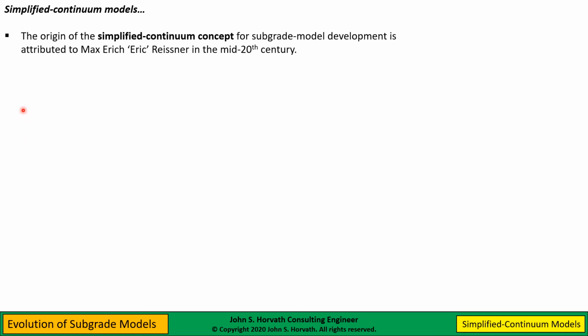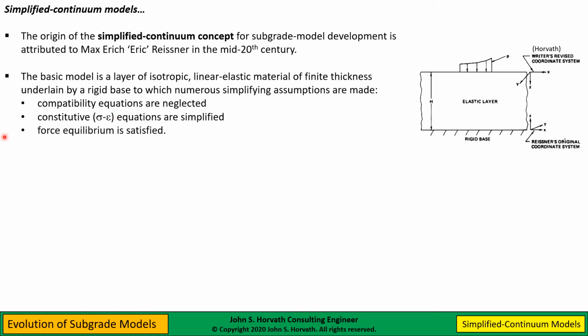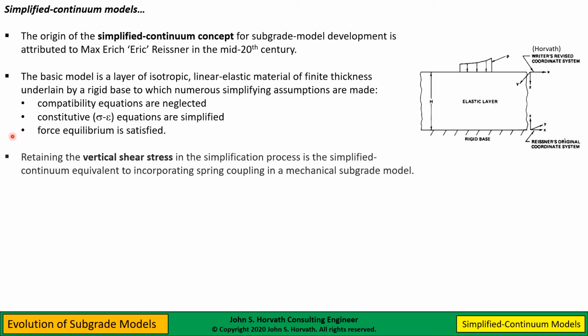Simplified continuum models really trace their origins to Eric Reissner in the middle of the 20th century. Reissner assumed an elastic layer of finite thickness, h, over a rigid base, and he made a number of simplifying assumptions. He neglected compatibility equations. He simplified the constitutive or stress-strain equations. He did satisfy force equilibrium.